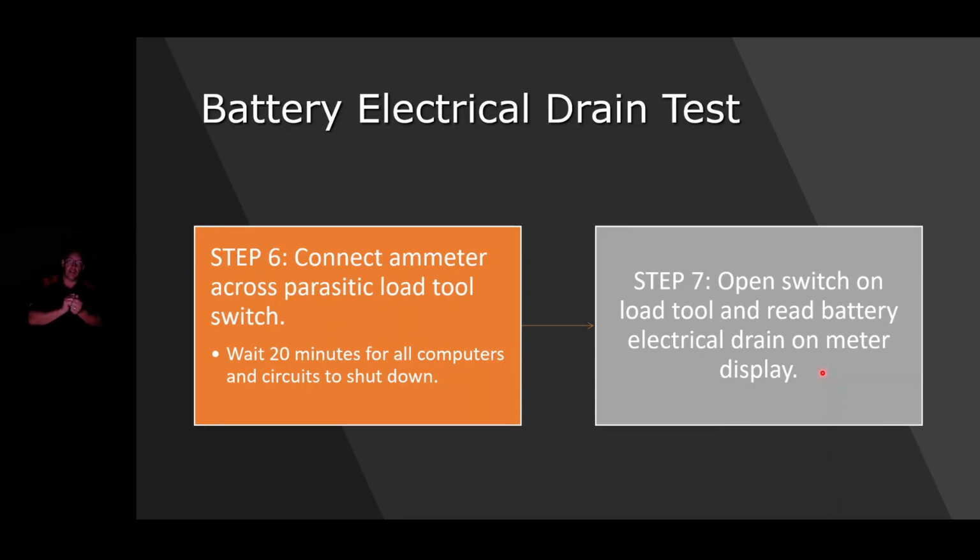And that parasitic load adapter is a special tool that you put on in the place of the battery terminal, and then you turn a little nut and it disconnects the battery. But what you do is you put your meter across that and then turn the nut and disconnect it, and then you force everything through your meter. And it's a great way to ensure that you don't disconnect the modules and all that stuff from power during the process of doing a parasitic drain, okay?